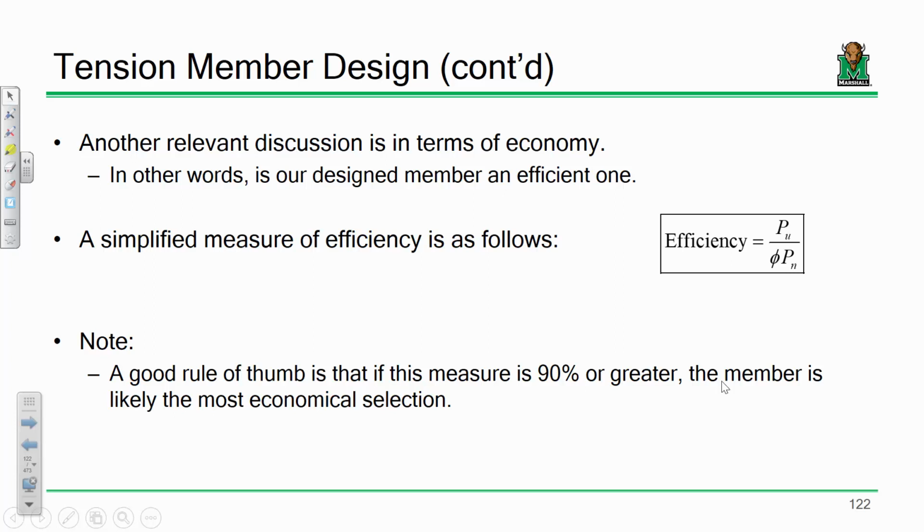But how do you know whether or not your design is good, okay? A good way of checking that is to compute its efficiency. And its efficiency is basically the load that's on the beam divided by the resistance, okay? You can sort of think of this term as kind of like The Price Is Right. You want that value to be as close to 1 as possible without going over, okay? If it goes over 1, what that means is that the loads are bigger than the resistance. If the loads are bigger than the resistance, what does that mean? Fails. It's going to fail, right? Because it's got more load on it than it can hold up. So you want that value to be less than 1, but as close to 1 as possible.